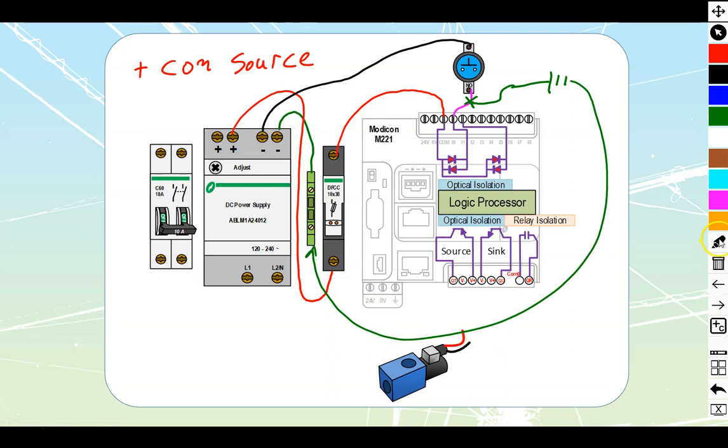And if you follow this through now, we see that we have power, comes through our fuse holder, comes into here, comes in through here, and then comes up, and here we hit that ground, and we are able to track a path all the way back in from here to my negative. In other words, a ground fault on the cable can cause operation of this type.